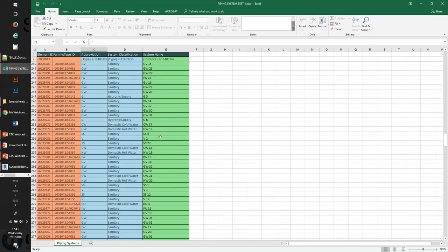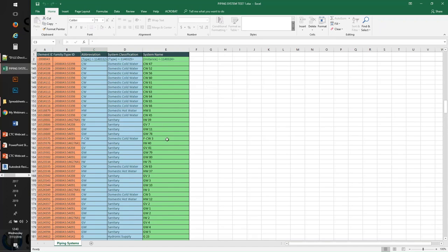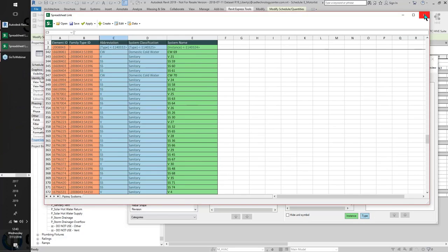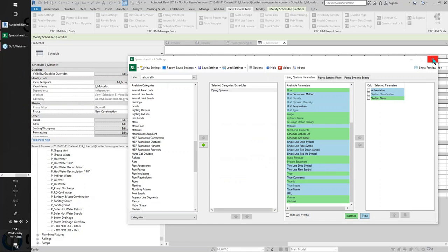It looks like I've got everything listed out. Let's just say the plumbing engineer is not happy with some of these abbreviations and thinks we need to change everything for sanitary, vent, and sewer to W. So we'll hit this, we'll save this, we'll modify the values,